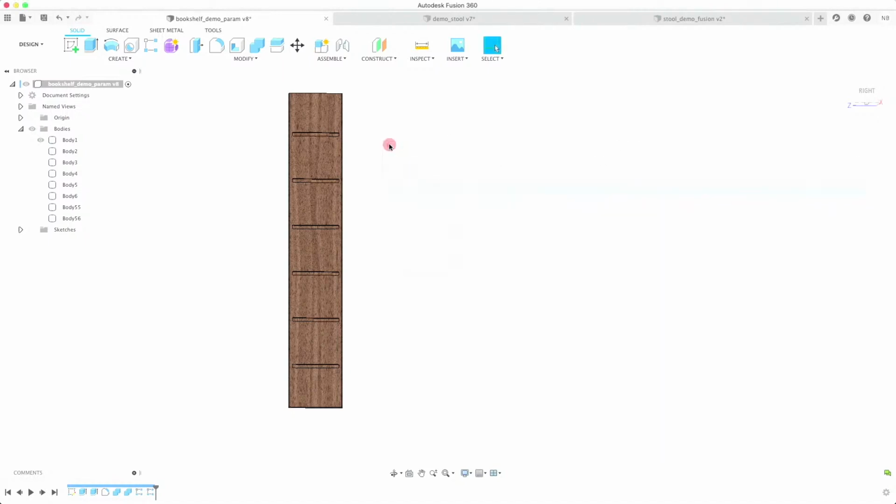So in this case, it's defined in the sketch for both of those guys, but you can also use variables or parameters rather in 3D operations. So for instance, the thickness of an extrusion that you want to make, that can be a parameter. So it's really, really powerful for those types of things where it's just like, man, if only I could just change that as many times as I wanted to.